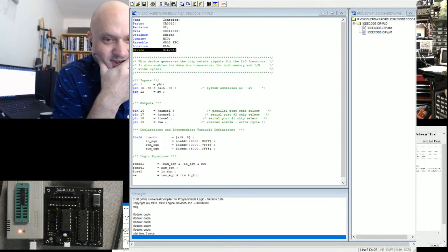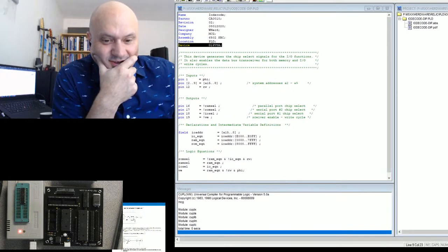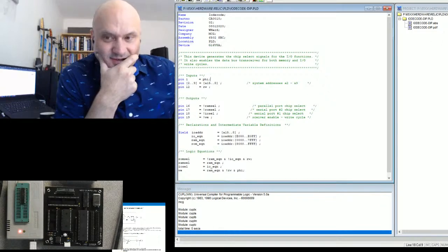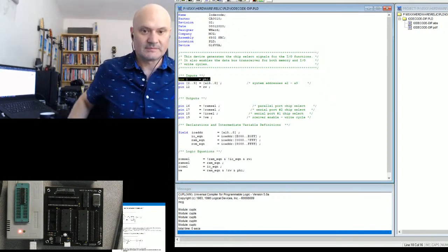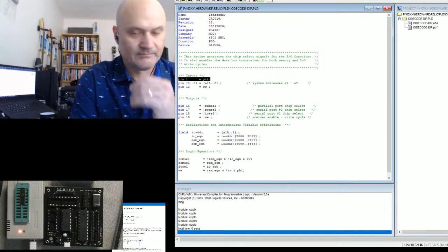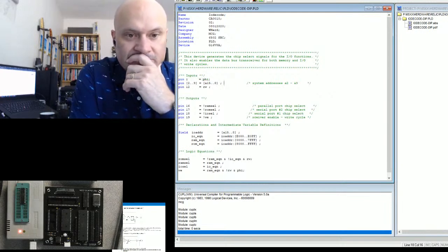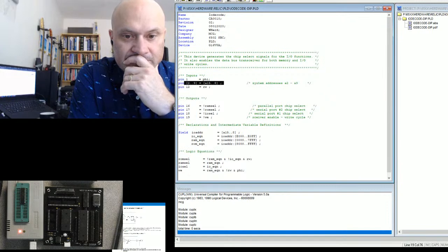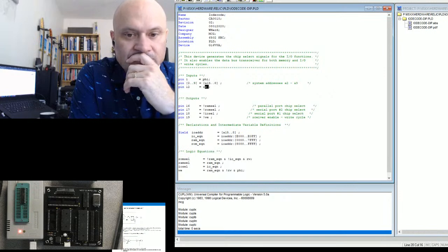Hello, Mondo 8-bit. So here we have my little tiny address decoder. And the very first thing we do is define the pins. So I've got the clock from the 6502. Why do I have the clock? That tells me when the address lines and data lines are valid. Then I've got the address lines A15 to A8, which means I can decode those upper nibbles that you were talking about. And then I have the read-write line. I need the read-write line because I need to create a gated write. So this thing does both a chip select and a gated write signal.